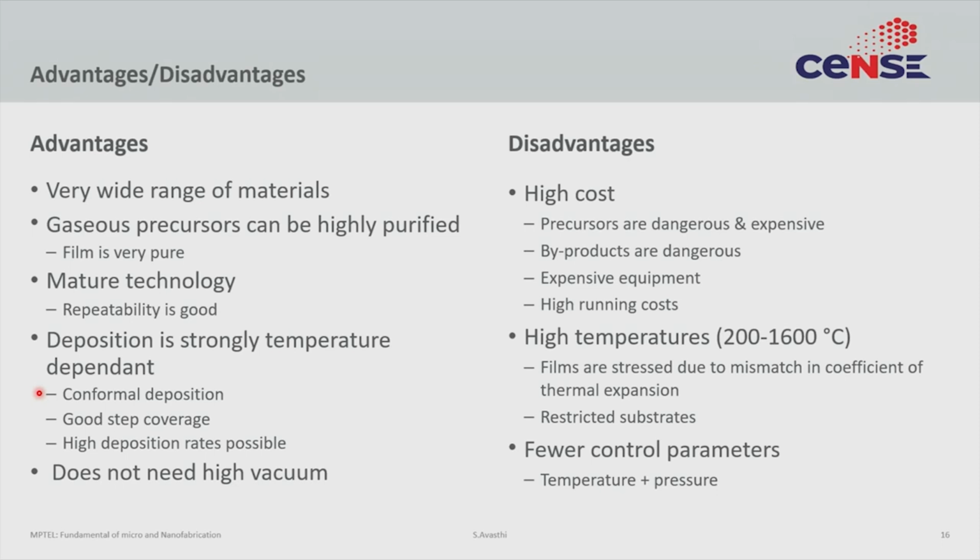And running costs tend to be high, because in order to do CVD right, or at least safely and in a repeatable fashion, there is a lot of supporting infrastructure that is required. You need exhausts, you need scrubbers, you need very good gas cabinets, you need gas detectors. The technique is a little complex, so you need very highly skilled workers, and all of this tends to add to the operation cost of a CVD equipment.